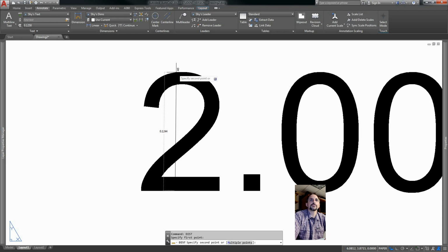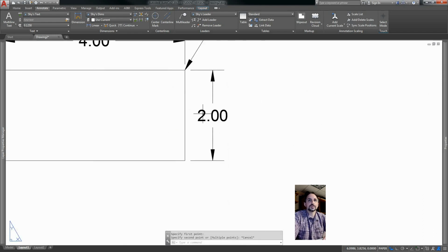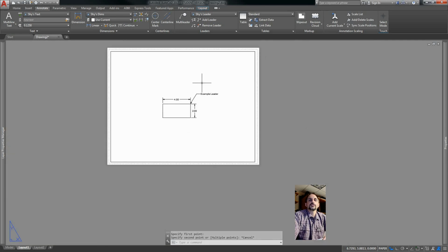And it is. Very good. So we've now adjusted the viewport scale, which has reduced the size of the object on the paper, but my text has not changed in height, indicating that it is set up as an annotative style and it is working properly.